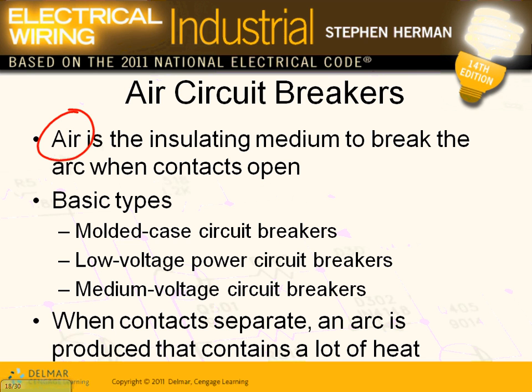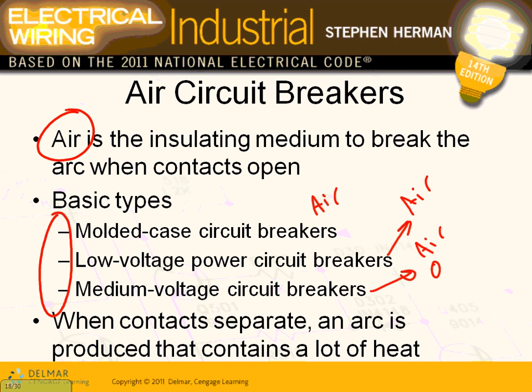There are also 3 technologies that they build the circuit breaker from. Molded case circuit breaker. Remember that? That's molded case circuit breaker. That's air circuit breaker, right? 99% of the time, air circuit breaker. And also low voltage power circuit breaker. It's also called air circuit breaker. These 2 are air circuit breakers. This guy is medium voltage circuit breaker. This could be air, could be oil, or could be vacuum. So these are 3 technologies.